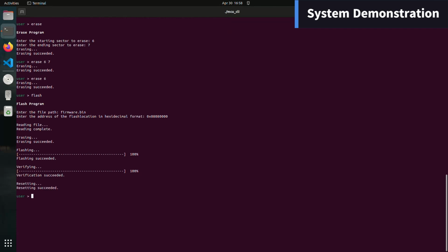So once flash is finished, it will reset the board, and to continue with other board related commands, make sure you re-enter your bootloader, by resetting the board and pressing the user button. Now we can independently call some of these commands that have been called by flash, like erase, flash, verify, by doing so. So the verify command is similar to the others.